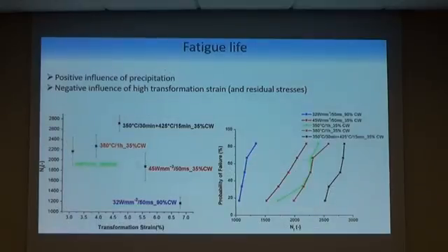And finally, the fatigue life of the tested wires, which is the most important result of this research. You can clearly see that the wires with the longest transformation strain show the worst fatigue life, only about 1200 cycles. On the other hand, wires with shorter transformation strain show much better results. And I should also mention that each type of annealing was tested 5 times, and you can see the scattering of each experiment.